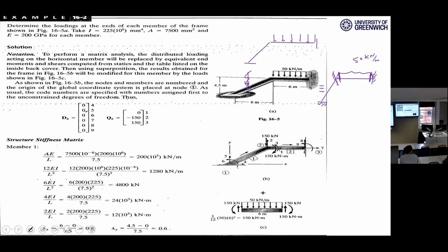So the question is, can I remove this distributed load and replace it with two sets of fixed end moments? The answer is yes. The fixed end moments are resultant from that distributed load. So forget about the distributed load, and I substitute it with two sets of fixed end moments. Okay? Set number left, set number right. This support here means I'm grabbing this point with my hand tightly, not to move and not to rotate. Okay, I'm just holding it.